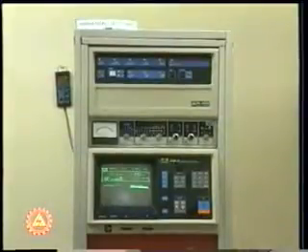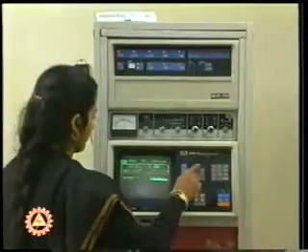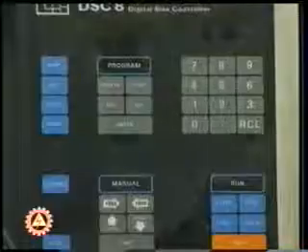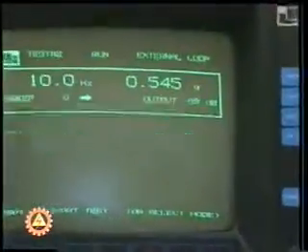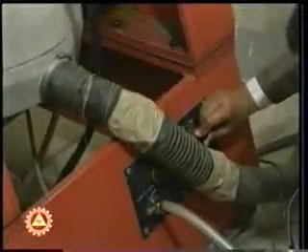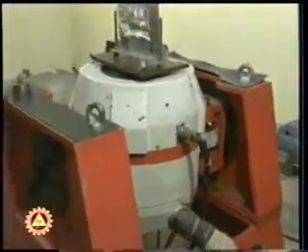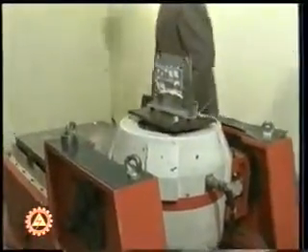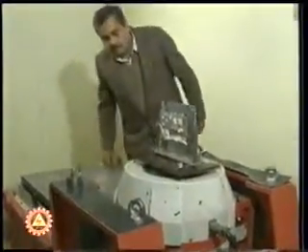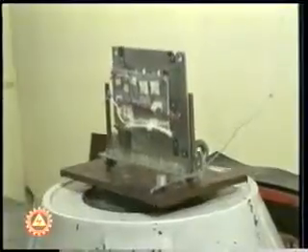On completion of burn-in tests, we place the system in a heat chamber for 5 to 6 hours. Finally, we subject the system to vibrational and humidity tests. We do it to ensure that the semiconductors do not fail for any reason after a few hours of operation.